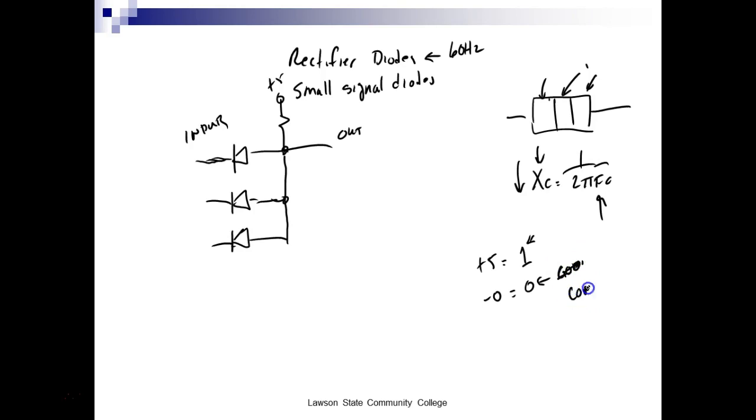So let's go common. So what would happen if I come over here and I put a 1 on all these guys here? They'd turn off because I got 5 volts on both sides of them. So I got 5 volts on here, 5 volts over there. The diode's turned off, right? You understand that?